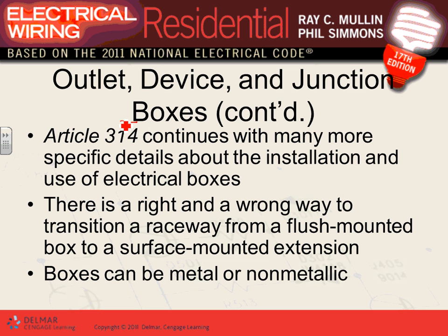We will come back, guys, to the rules of sizing a box in detail. And then the boxes can be metallic or non-metallic. Almost exclusively when we're working in dwellings, we use non-metallic boxes. When we go to commercial, industrial, hospitals, you name it, almost always we use metallic boxes. That's kind of the divider between them.